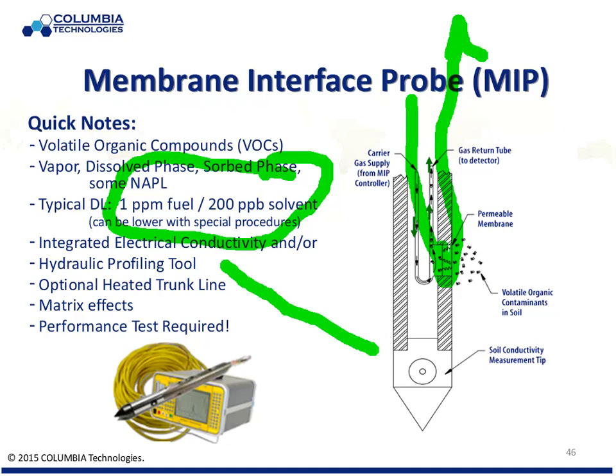I would point out here, as I said, all of these are what we call qualitative instruments. They're helping solve the problem by getting thousands of qualitative data points and really working on the geostatistical challenge. That said, they all have performance test procedures, and they should be performance tested. You ought not be operating with tools that you don't know what their response factors are, so you can have consistent data. They're all operating in what we call a direct sensing or direct contact mode, so you don't have a volume, and therefore you're not going to be able to calculate a mass.